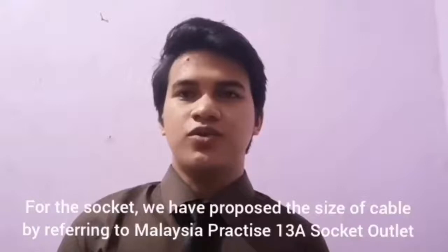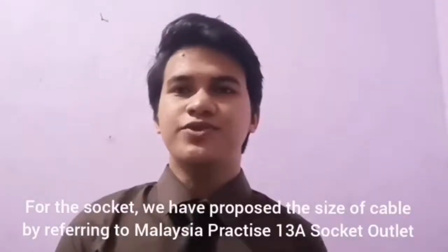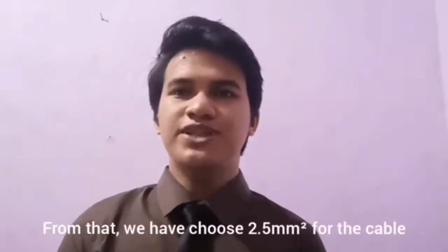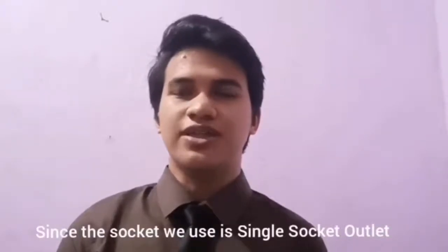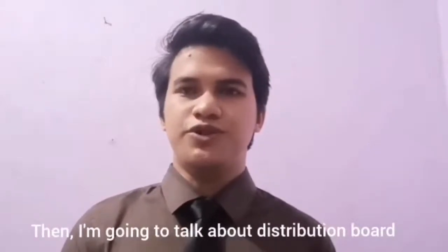For the socket, we have proposed the size of the cable by referring to the Malaysian practice 13 ampere socket outlet. From that, we have chosen 2.5 mm square as the size of the cable, since the socket we use is single socket outlet. Then, I'm going to talk about distribution board.